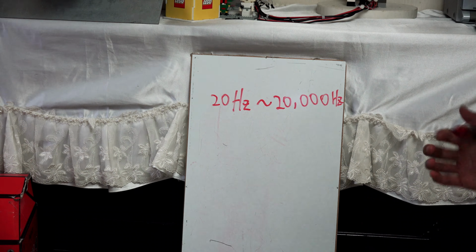So you first have to digitalWrite LOW, and I will write delayMicroseconds for 2, and then, like we saw in the data sheet, I will set it HIGH for 10 microseconds and then LOW, and this ultrasonic sensor will send HIGH for the duration.